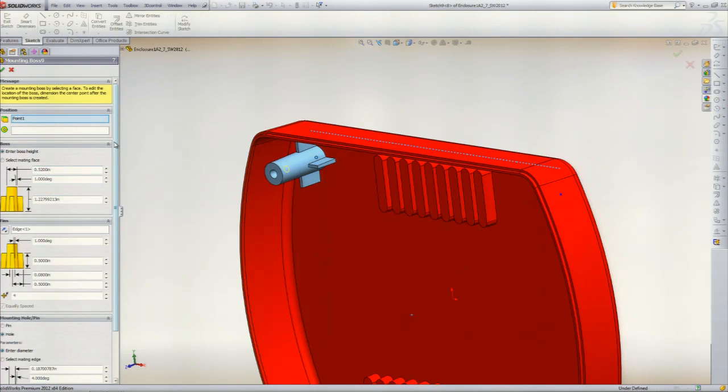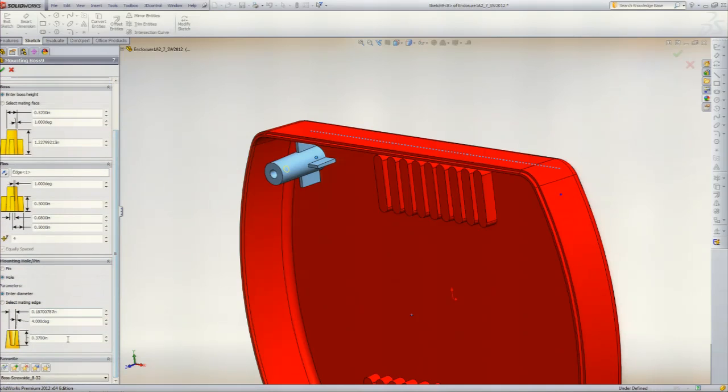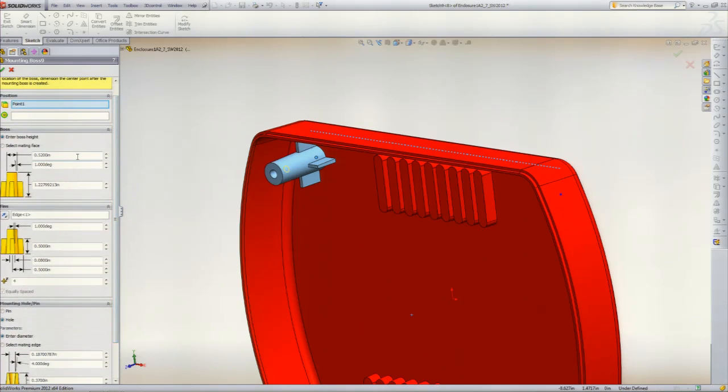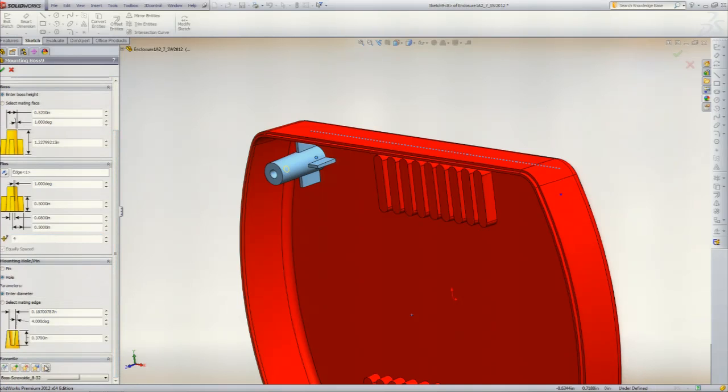See, here, my favorite for this particular boss, you can see where all my fields are filled with different dimensions. These I had to do ahead of time. And then I go down here and just save the favorite. This is for an 8-32 screw. You can see boss screw size 8-32.